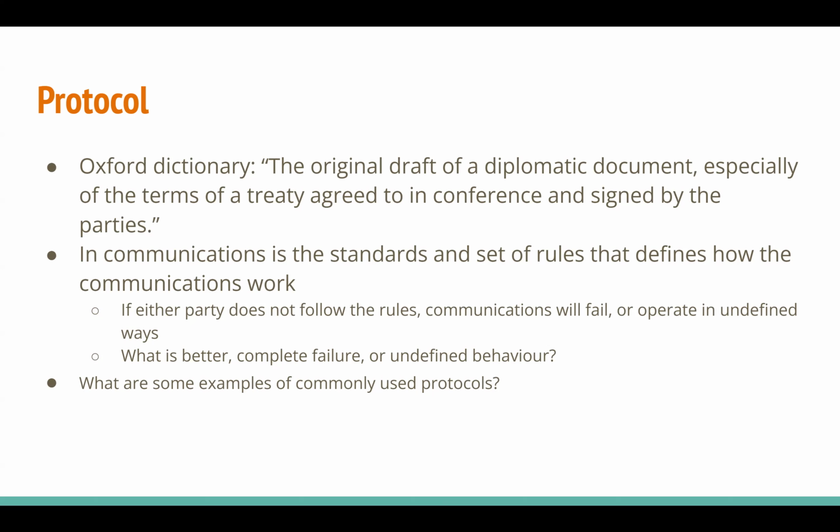And so then what you'll see very commonly is two devices from the same manufacturer will talk over a protocol just fine. And then you add in a device from another vendor, and then all of a sudden that one can't communicate to the other two. And so then people start blaming that new device that came in when realistically they might have even implemented everything correctly and the original ones didn't, but they implemented it wrong in the same way.